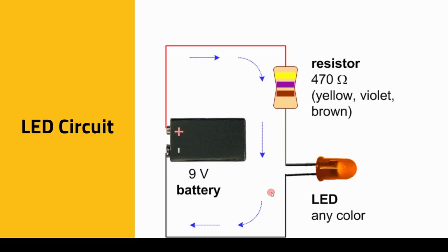And this is the example that I was talking to you about. If you have a 9 volt battery and you have an LED, what resistor do I need to use so that the current through the LED is not excessive and it doesn't burn up, and how do I calculate that? So I figured out that this is 9 volts, the drop across the LED is 2 volts, so I need to drop 7 volts across the resistor. And then if I know the current that needs to flow through the LED, then because I know the voltage drop and the current, I can find the resistance, which will be V upon I, which will give me the value of this resistor.